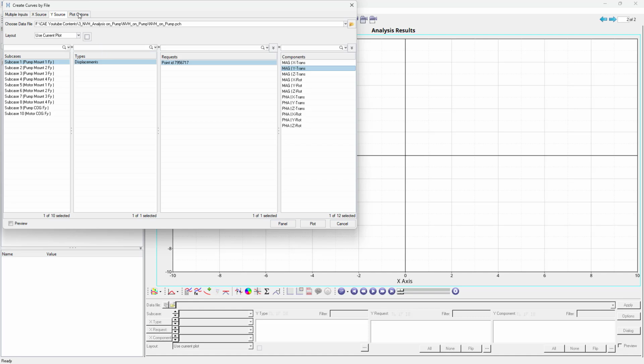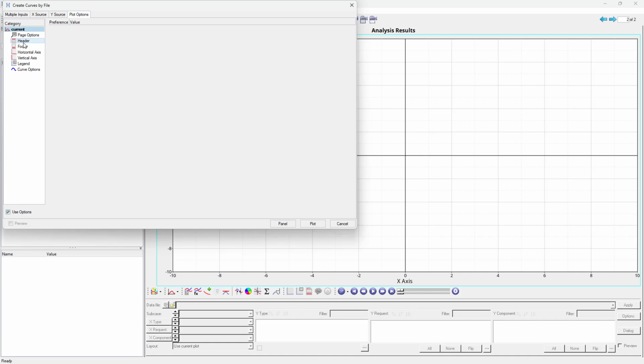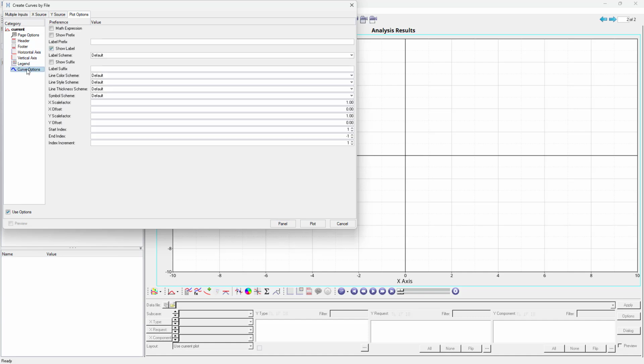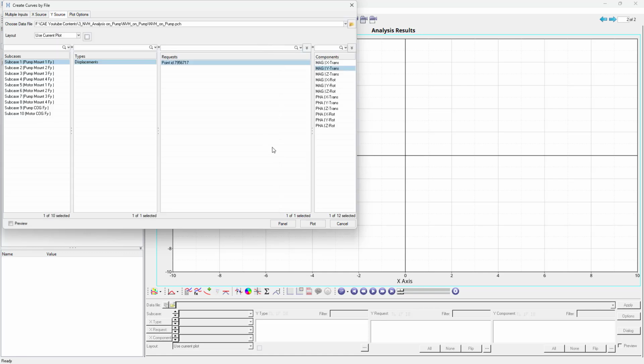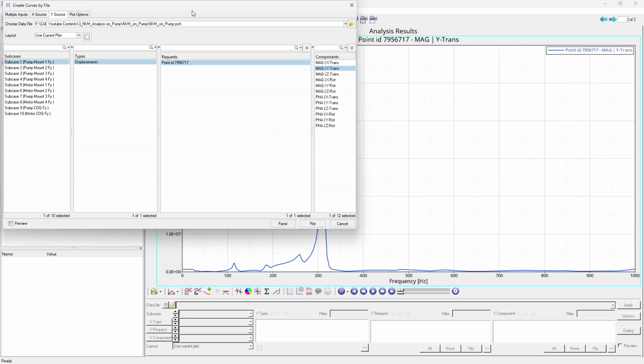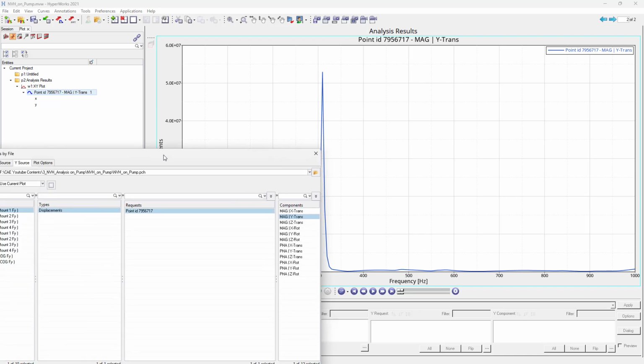Correct. Before doing it, I would like to consider the stiffness as a reference. For that, I'll go and change the math expression from displacement to stiffness. So how are we going to change it? Inverse of displacement is stiffness, right? So you can just do 1 by V. So in short, it will be considered as stiffness. Correct. You can even take it as displacement. If it is displacing more, then anyway the stiffness will be less. But right now I'm considering the stiffness directly.